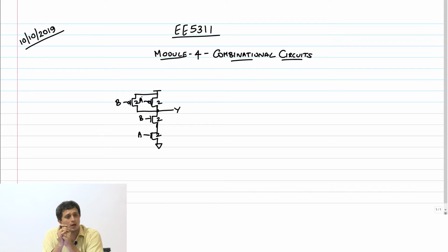Okay. Now my question is, logically, these two inputs are identical. I can swap these two and still not change the logic of the circuit, right? I can't do this, of course, with A plus BC. I cannot just swap any of the inputs. Logic will change, right? Now, when the logic is identical, which input should I feed to which transistor? Is there a choice? Are they equivalent or not?